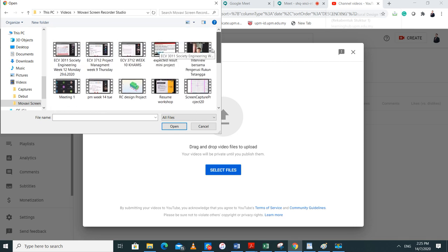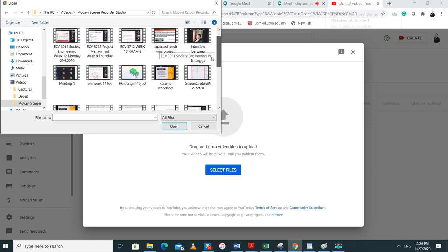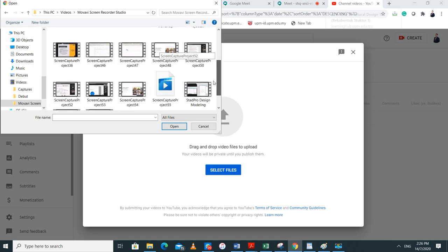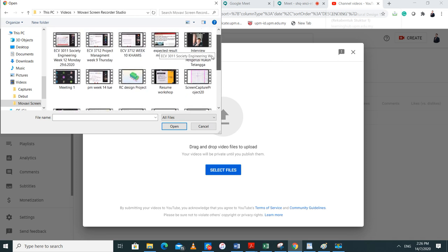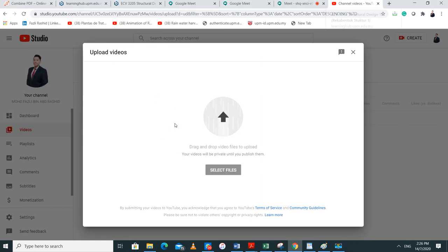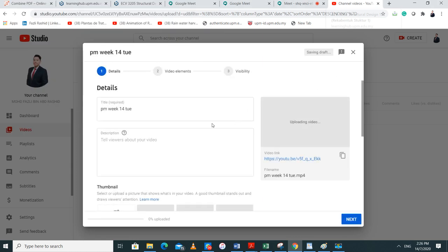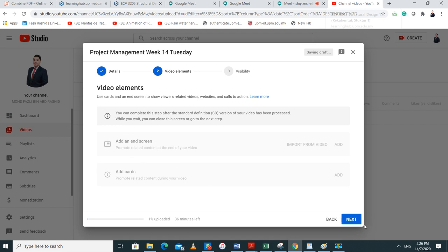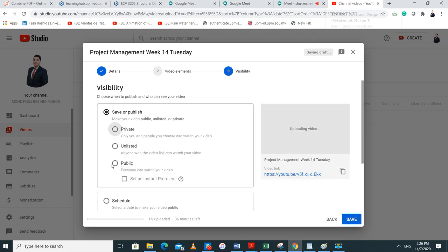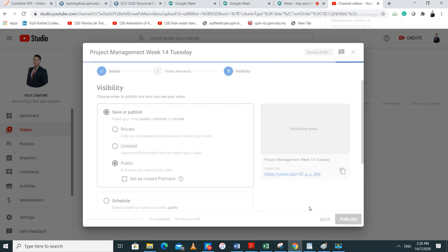In SPT, the value that we obtain is N, the penetration resistance of the soil, and N multiplied by 4 from the SPT is equal to Q sub C. If you have the Q sub C result from the CPT, you divide it by 4 and you get N. If you do the SPT test, you multiply by 4 and you get Q sub C. That's just a relationship that you might find useful.